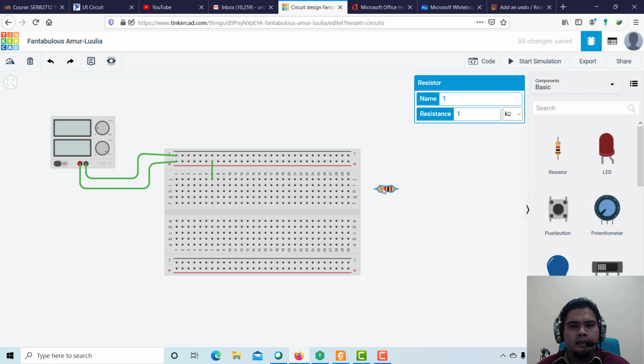So then I connect into any port over here, any point, any hole in this row 7. I just choose the last one, that one. Why I choose the last one doesn't matter. You can connect here, here, or here, because all these holes are connected together with this point, which you already connected, and they are all connected in wires there.